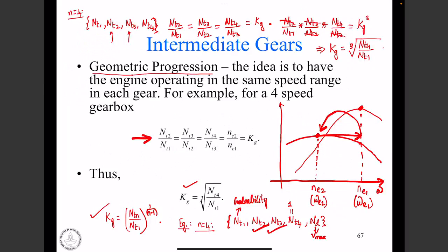So in this power rating graph you build, can I go much beyond this power rating also? You mean after the peak? Yes, after the peak. If I don't need that much torque for my vehicle, what will happen is that if you go beyond that, the torque that you require will fall down. If you have loads which don't require that much torque, the vehicle will still respond and the speed will keep on increasing, is it not? But by design we essentially take it slightly to the right of the maximum power point.